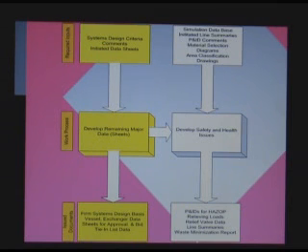But before we go to the next issue, we review the P&IDs for safety issues. Relief valve analyses get done. Insulation is firmed up. And those kinds of issues are reviewed in-house, mostly under the direction of the process engineer responsible for the P&IDs.